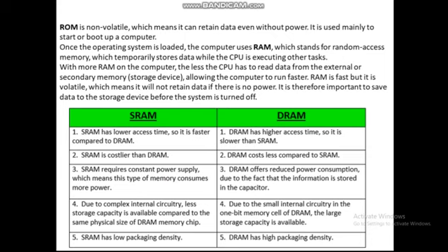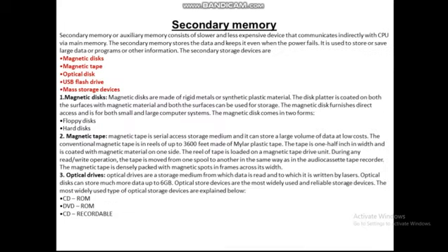A DRAM needs only one transistor per memory cell, and its packing density is high. A DRAM consumes less power, and SRAM uses a conventional flip-flop containing two cross-coupled inverters to store the binary bits ones and zeros. There are synchronous DRAMs also, synchronous graphic RAM, then double data rate, which is an advancement over synchronous DRAM. All such things are there.